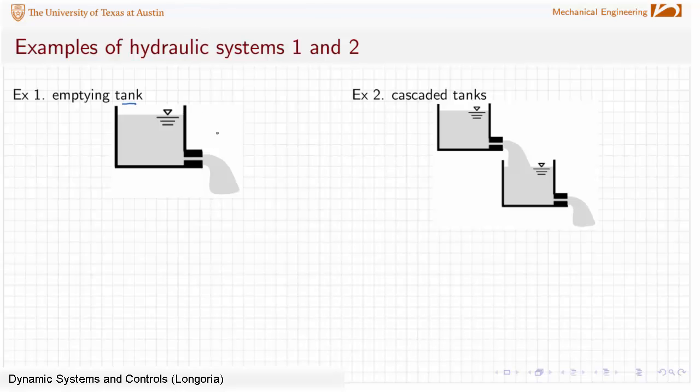So, I like to use this example in contrast to, say, if you had a tank that was long and thin, because in this case, we like to think of a tank as being sort of a wide aspect ratio. So the water, if you think about it, the velocity is falling at a relatively slow pace such that you can make the assumption that the hydrostatic pressure at the bottom of the tank here is rho g h. And when we make this assumption that it's quasi-static, it means that we don't have any dynamic pressure down here, right?